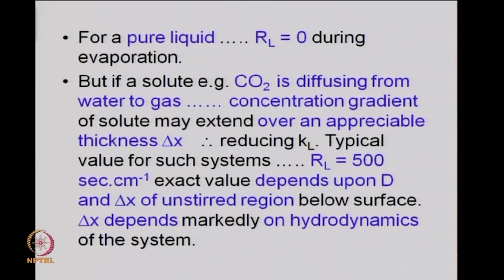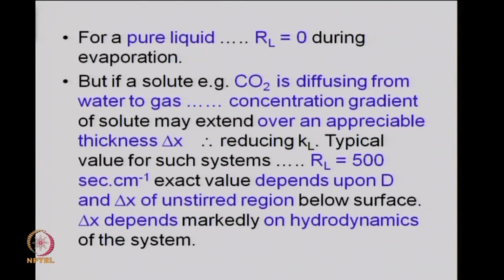Please. RL, that also occurs due to that collision barrier inside the liquid. RL again will depend on the way transfer is taking place, it will depend on the thickness of the liquid which is involved. So, if it is unstirred liquid, then you expect the resistance to be highest. If it is a stirred liquid, then the stagnant layer close to the interface will be smaller. It arises due to the collision barrier. It arises depending on the thickness of that stagnant layer, and that thickness of stagnant layer will depend on the agitation in the bulk.